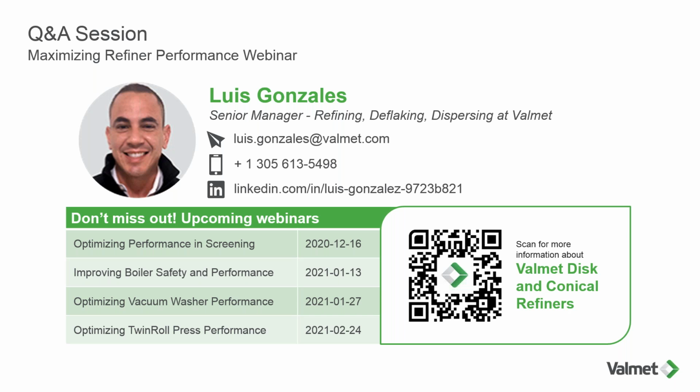We're going to identify whether it's a rotating assembly issue, whether it's a tram alignment issue, and generally if we find a tram alignment issue, we're going to fix it right in place. So we're going to tram your refiner as long as you're willing to work with us. Some of these trammings take a while because at the end of the tramming you've misaligned your main motor as well, so you're going to have to be willing to realign that main motor as well. But we're willing to do this with you. Again, that takes about 1/3 of a day per refiner, so we can definitely hit at least 3 to 4 refiners if we have the right crew in place.